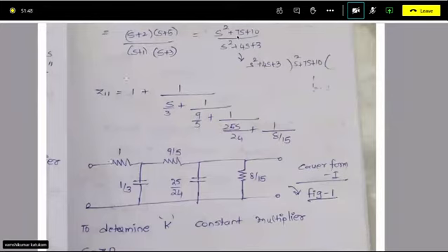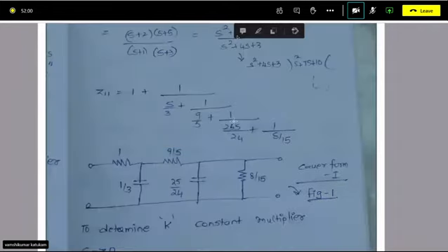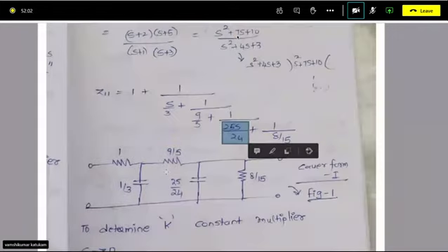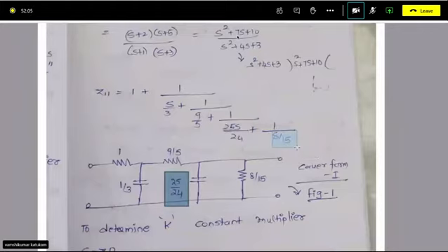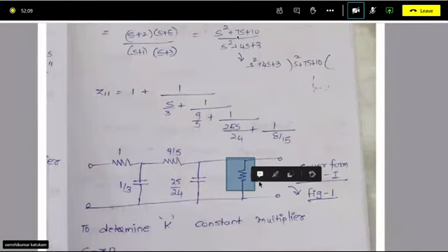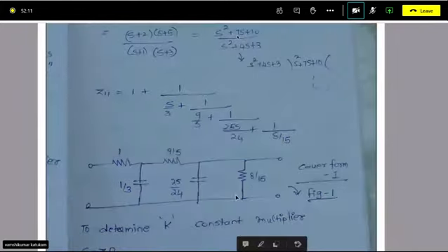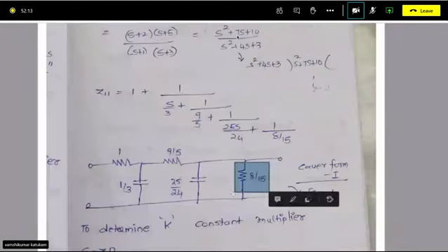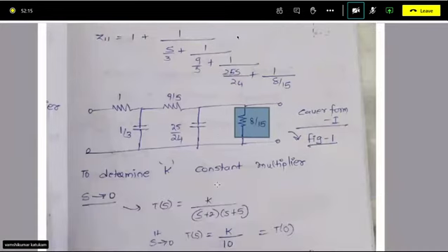So starting with its impedance, 1 is there, so that's why it is starting with 1, and you have S capacitor 1 by 3. Again a constant, you will have a resistor, and again you have S, 1 by SC, 25 by 24, it will be a capacitor. And you have a constant. Finally you are ending with a resistor because there is no capacitor after that. So 8 by 5, you have this 8 by 15. Okay, this is your K form 1.